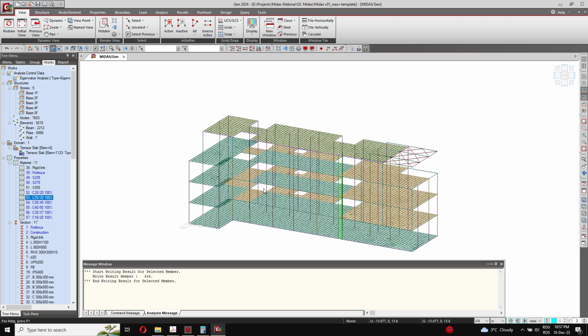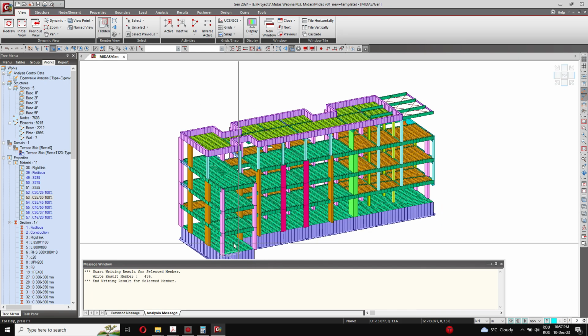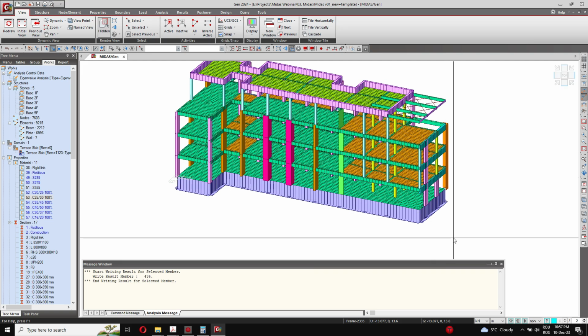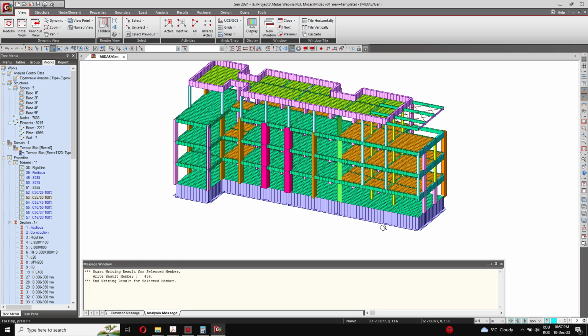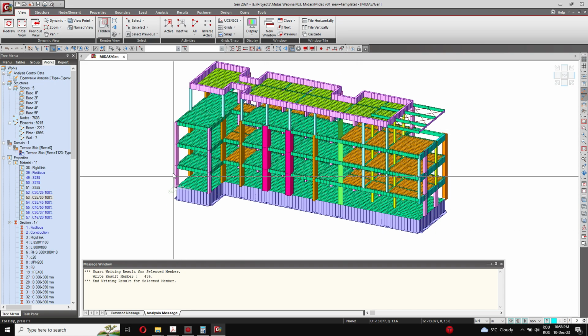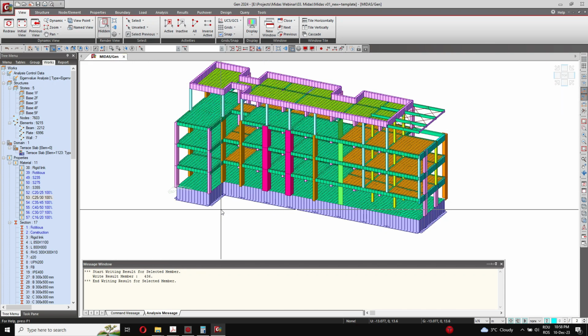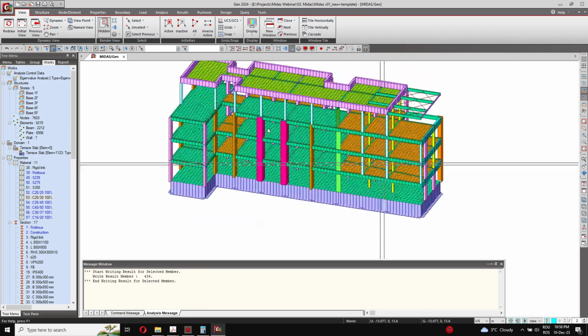So this is what I wanted to present. I focus mainly on the modeling part because you saw it's very easy to build a model in Midas. My approach is to use some CAD files in order to build 3D geometry using lines in different layers, and then the layers from the CAD file must correspond to the section you want to assign to the model.